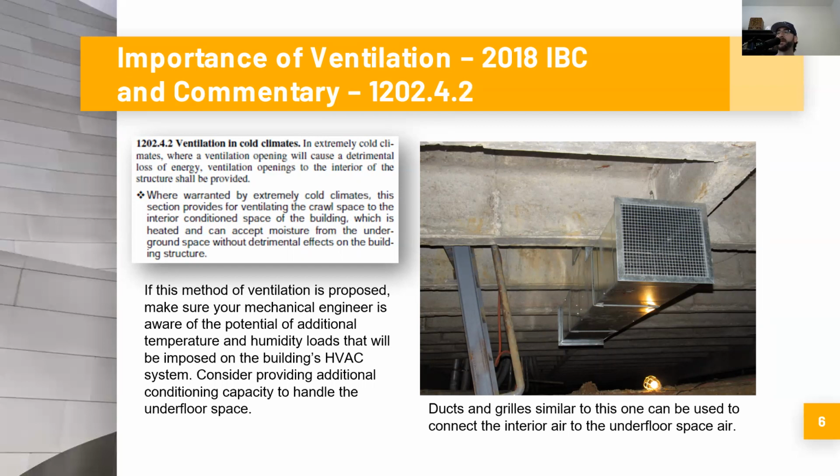So this photograph is a duct penetrating the floor above, and it's open into the underfloor space below. Systems similar to this one can be used to connect the interior air to the underfloor space per this section of the code.